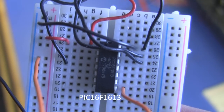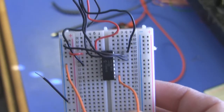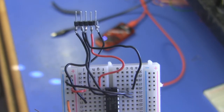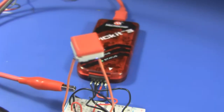I've used a PIC 16F1613 for this, a small PIC device. The only critical factor in choosing the PIC for this is it needs to run at a 16 MHz internal clock speed. And that is so we can meet the timing requirement for the WS2812.